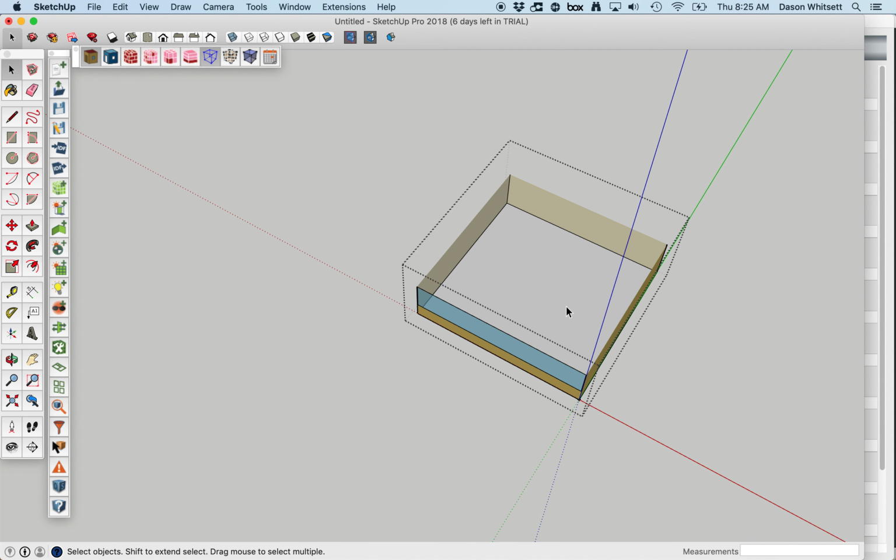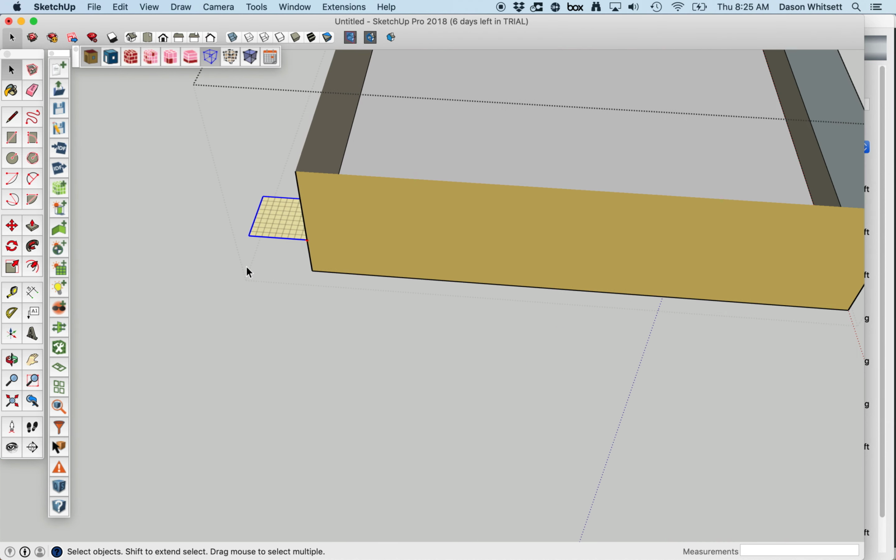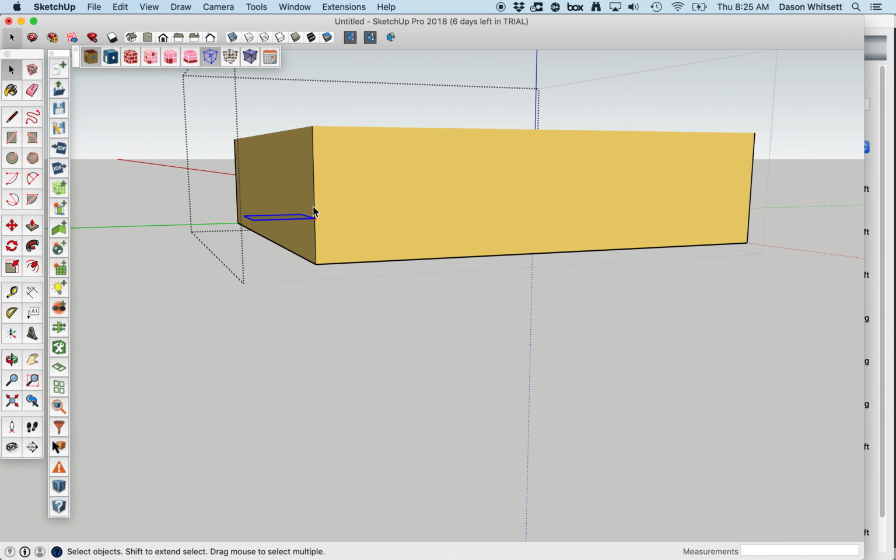I'm going to double click to edit the space. The first object I'll put in is the illuminance map that I just mentioned. It's this tool here. I'll click somewhere within my space and snap there. I can see that right now it's outside the space, but it came in a little bit above the floor. Sometimes it will come in at a height of about 2.5 feet, which is generally where you want it to be. Sometimes it'll come in flush with the floor.